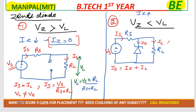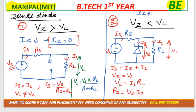As you know, here the voltage across load resistance would be VL, voltage across Zener would be VZ. So can we say that VZ is equal to VL because these are connected in parallel? Exactly. So according to Ohm's law, we can also say that VL is equal to IL into RL, right? And for PZ, power across the Zener diode, that would be VZ into IZ. Okay. Now one more formula left, that was for IS. IS would be how much?